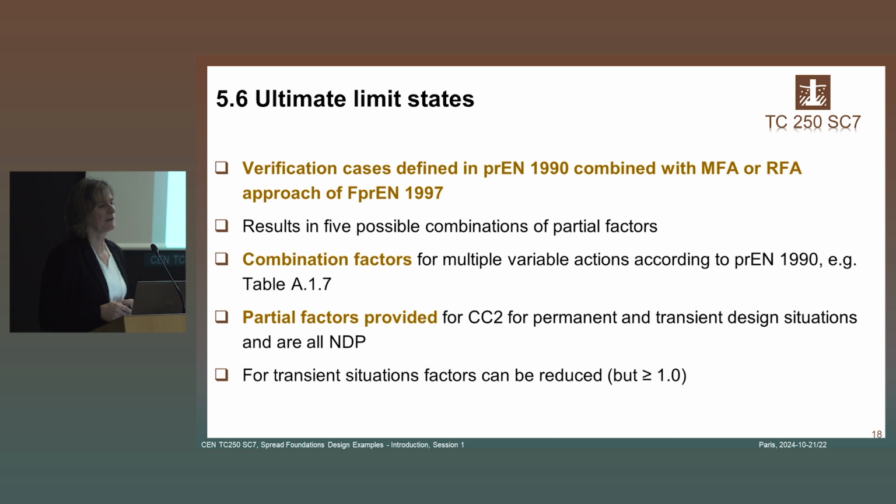So here, regarding the partial factors, you have to establish verification cases in regard to the actions or the effect of actions, which are defined in EN 1990, which will be combined with either the material factor or the resistance factor approach, which is regulated in EN 1997. And this ends up in 5 possible combinations of partial factors. But just to say it from the very beginning, that doesn't mean that you have to calculate all 5 calculations.